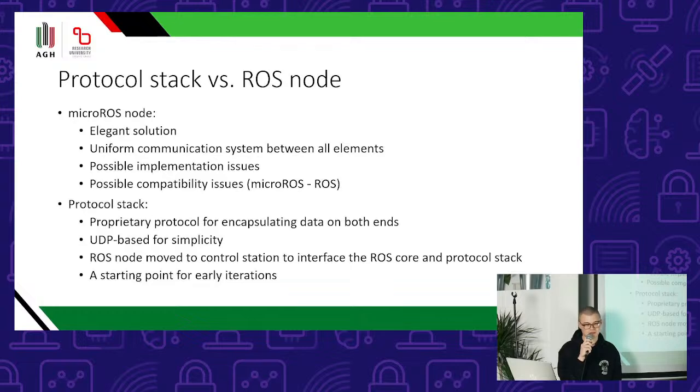But it raises some compatibility issues because there are new versions of the full Linux ROS. I think they are newer than the current micro-ROS version, and I believe it might create some issues with interfacing all this together. The other thing is possible implementation issues. We would need to integrate ROS into our current embedded firmware, which might not be very easy.